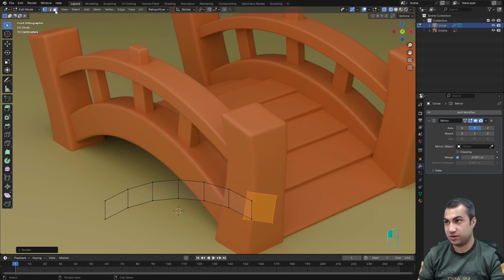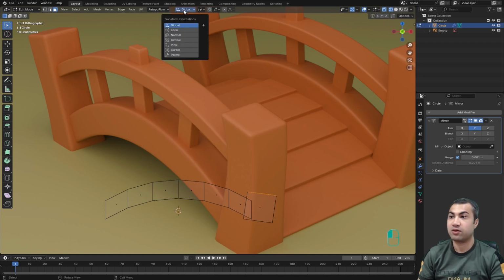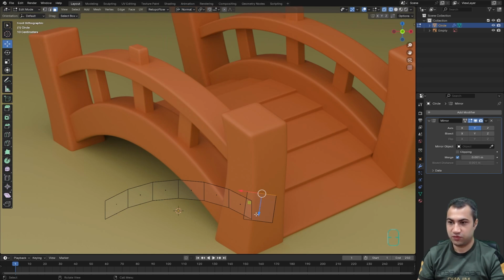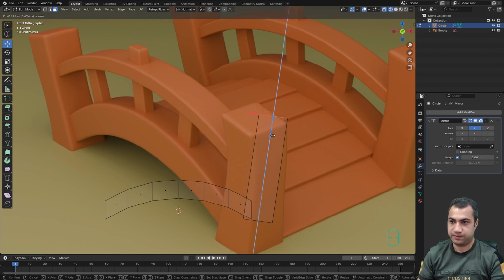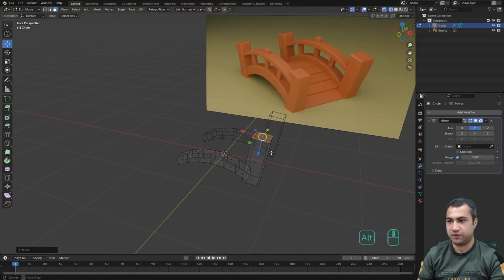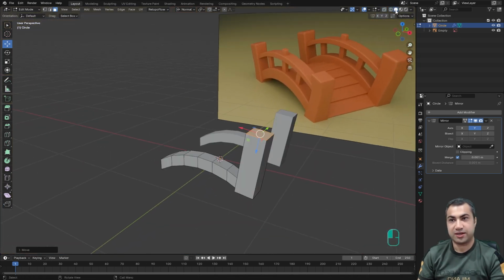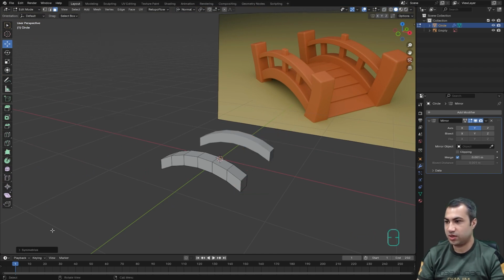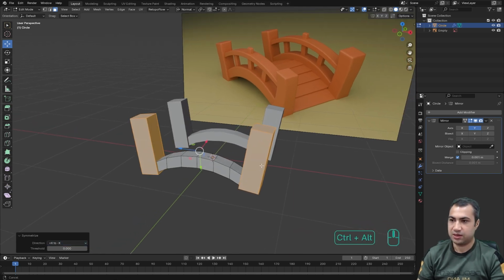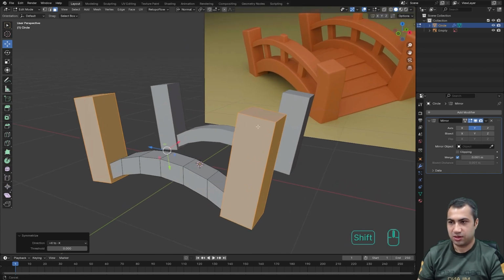Now I select this face selection, select this face, and from global I go to the normal axis and use the move tools to move it along the normal. And this much is, I think, enough. Okay, now I can select the whole cube and go to the mesh, symmetrize, and go to the setting from +X to -X. And I created these columns.